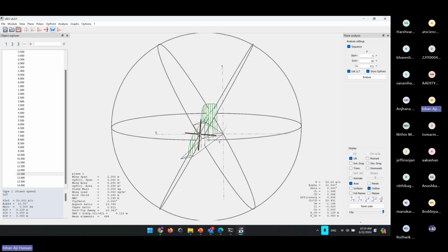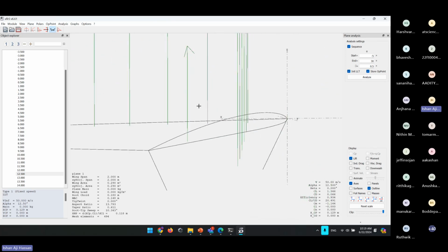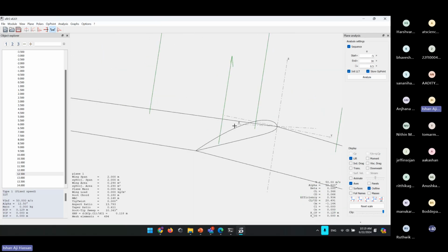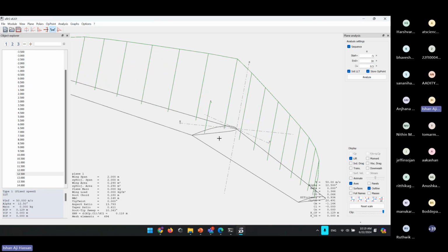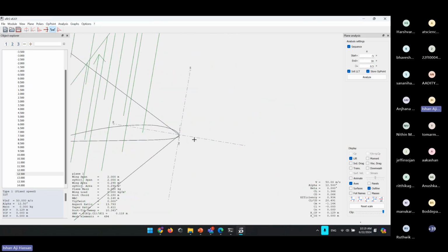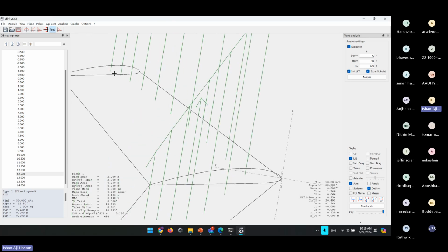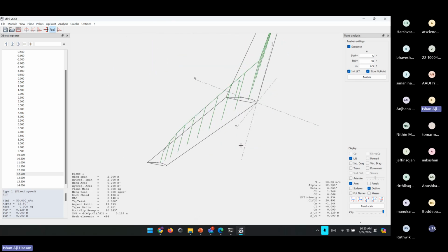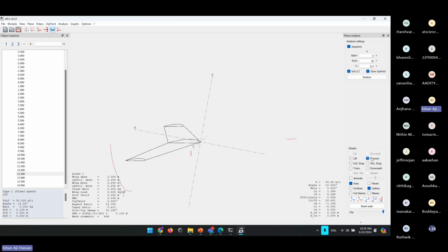So yeah, this is the lift distribution. Again, you can note how this is the overall averaged position. This is the overall lift arrow, the total lift representation, this one in the middle. I think this is the average position of all of these arrows on the x direction. That is why it's a bit further back than you would expect. These individual points at which these are acting are the centers of pressure of each of those wing sections, which move further and further back because your airfoil sections are moving further and further back. So yeah, that is it about the lift and moment I've shown you.